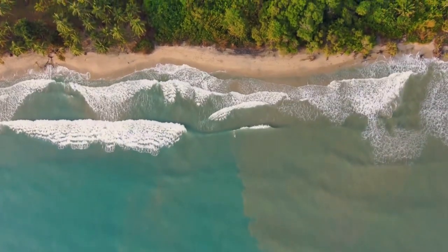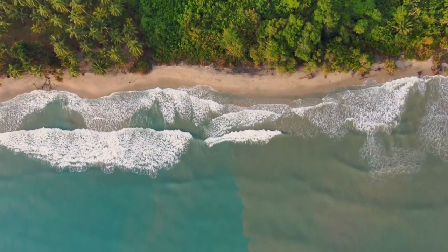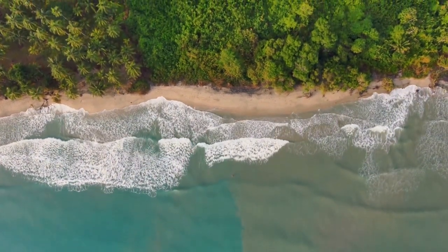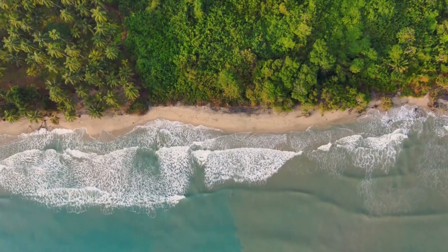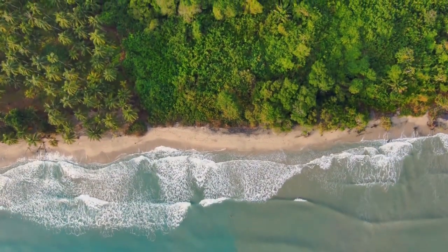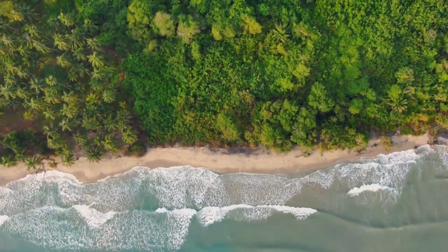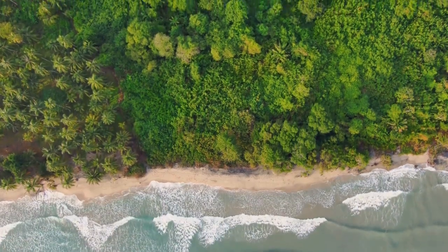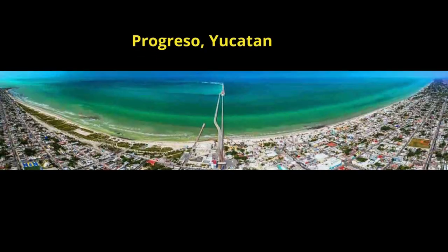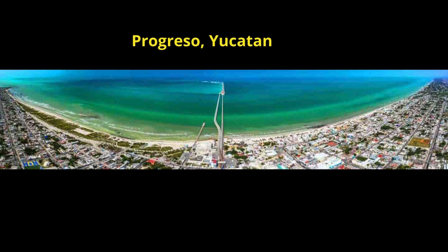If development of coastal zones is carried out maintaining the natural coastal dynamics, engineering interventions will not be necessary. However, we are aware that the development of civil works in coastal areas occurs, and sooner or later, changes in littoral transport will occur, leading to modifications of the coastline.